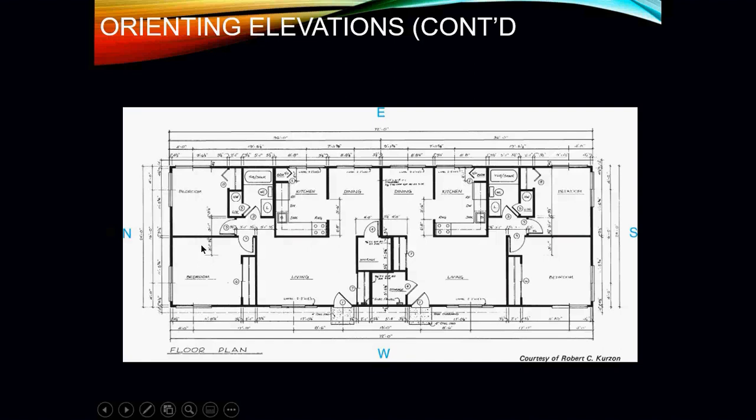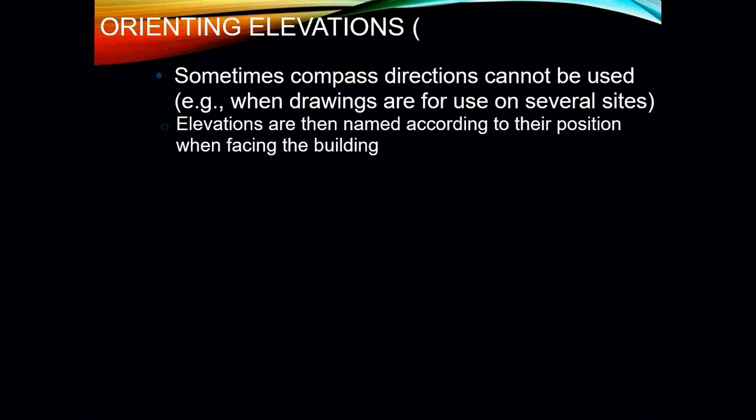So what you need to see with this is you need to figure out however big a room is using a floor plan, because you can use that to calculate your CFMs for a room, to see how many CFMs of air needs to be brought into a particular room based off of the square feet. You can also use that to orientate yourself, again, north, south, east, and west, of where certain objects and components are going to be located, such as maybe supply air diffusers, maybe your return air grills. You can use a floor plan like this to figure out where things go.